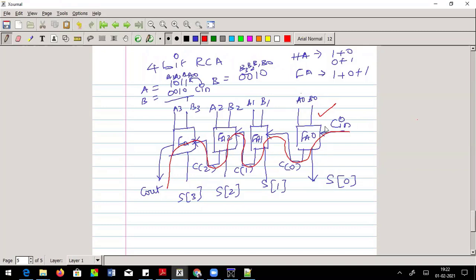Because already you have written code for a full adder. How does a full adder look like? Right? Okay. So this is a problem for a ripple carry adder. Otherwise, it is a modular adder where your structure keeps repeating. The output is typically like this: n plus n gives n plus 1 bits as our output.